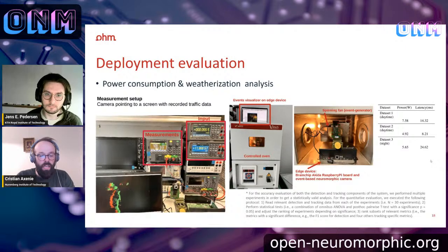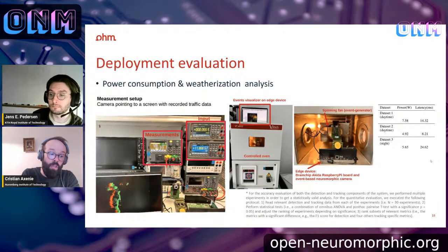But if we look at really also exploiting other advantages from the accuracy point of view, indeed, one spends more time in tuning this network, which one can do in Edge Impulse, actually getting into the code and tuning the network itself. Also in the quantization library from MetaTF, from BrainChip, you can tweak the parameters even more and take the accuracy to a different level.